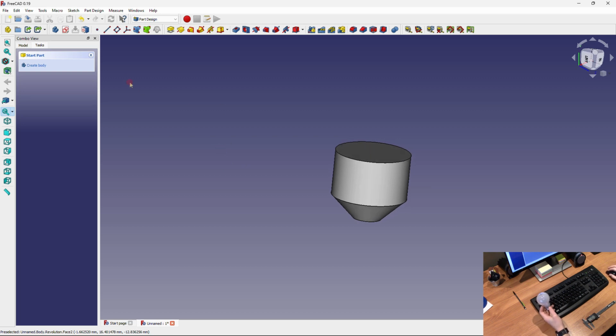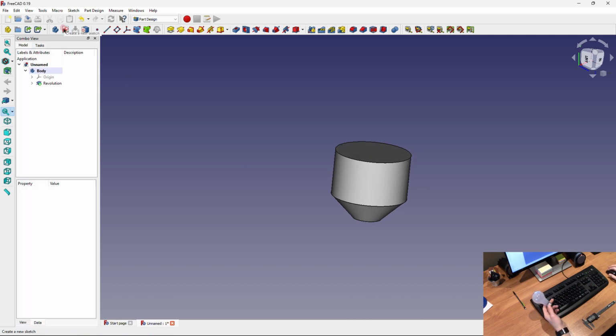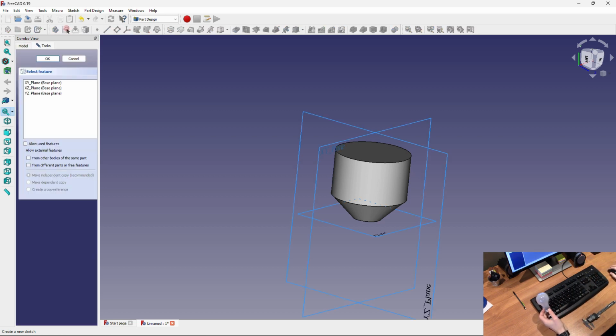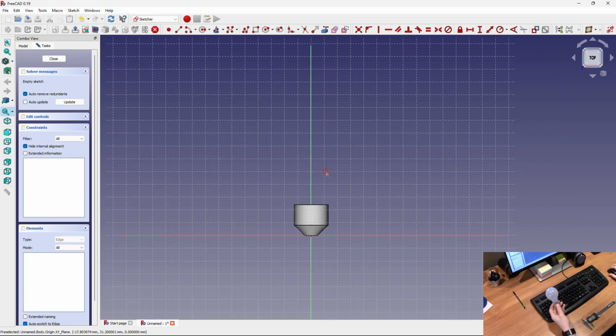Now, let's create another sketch, and this will be the main body of our light bulb. It will be on the XY plane, the base plane again. So, first of all, we need to measure the bottom of our light bulb, and it's slightly larger than the plug, so we'll have to put a fillet in there eventually. The bottom of the light bulb is 28, so that'll be 14 when we divide it by 2.